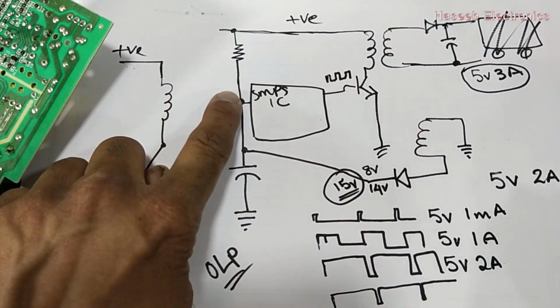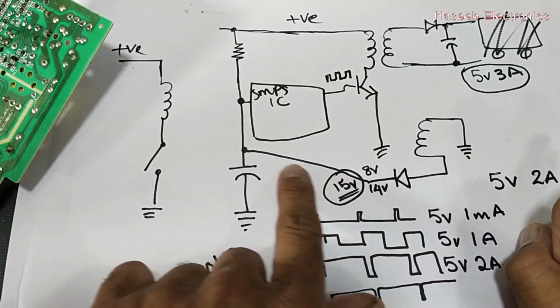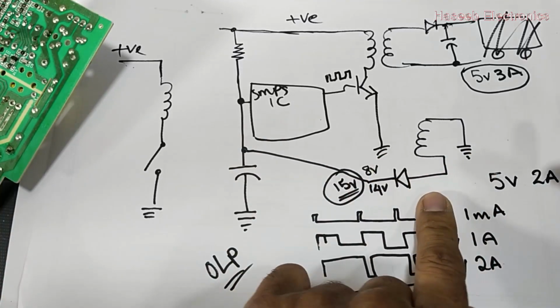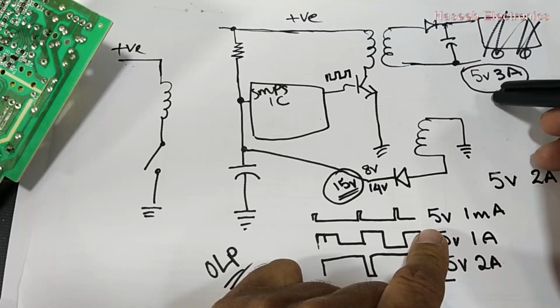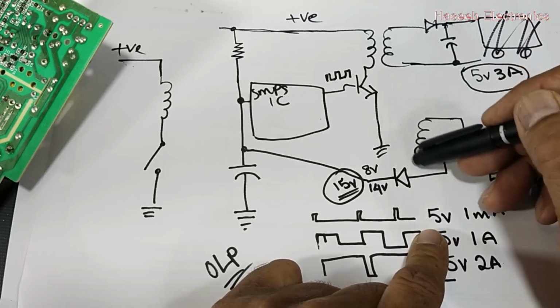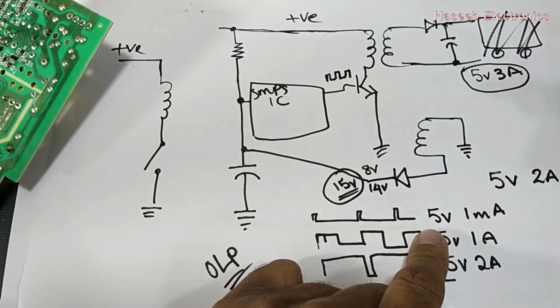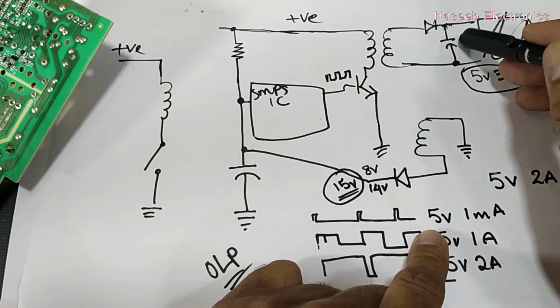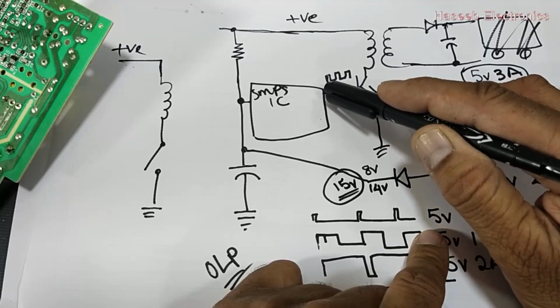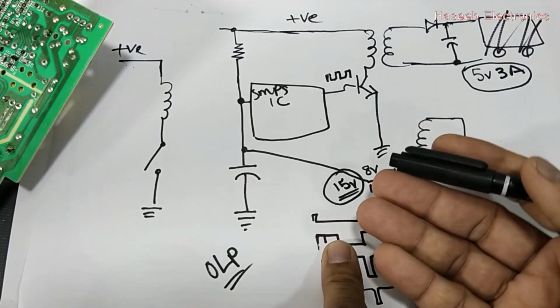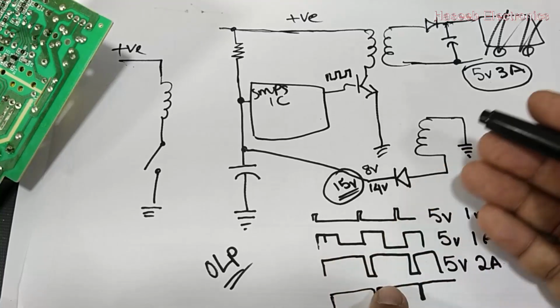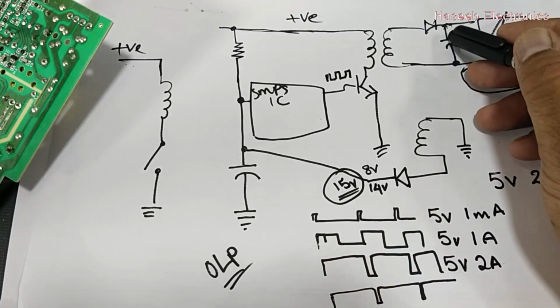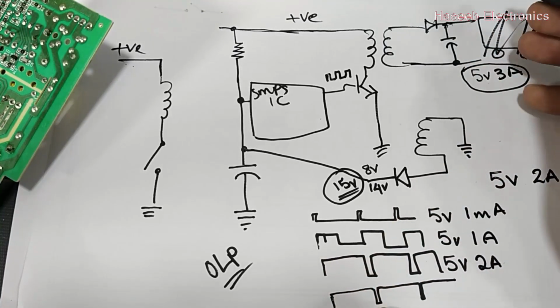First condition, soft start. Second condition, smooth operation. Third condition, the maximum load sensing circuit is also configured in this winding, because here we have load. To compensate the load effect, we have to increase the duty cycle. When it keeps increasing the duty cycle to compensate the load, either there is a short circuit or there is an overload.